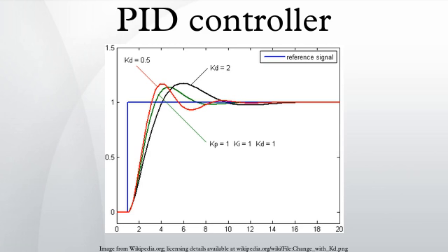A more complex control may include derivative action. This also considers the rate of temperature change, adding extra hot water if the temperature is falling, and less on rising temperature. Finally, integral action uses the average temperature in the past to detect whether the temperature of the container is settling out too low or too high and set the tap proportional to the past errors. An alternative formulation of integral action is to change the current tap position in steps proportional to the current error. Over time, the steps add up the past errors.